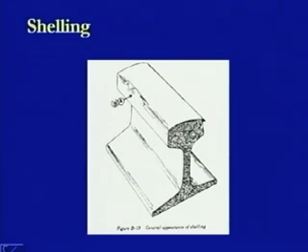So, what we found is that this much amount of mass has got removed from this location and it has fallen down. So, this is the shelling taking place. The shelling may be, at this location, if we look at this side, some material has come out of this location, whereas the head of the rail section remains like this. So, there is again a sort of canopy created at this location. This is another type of failure which can be there because of shelling, and this is being categorized as C, whereas here the two types of failure taking place are categorized as A and B.